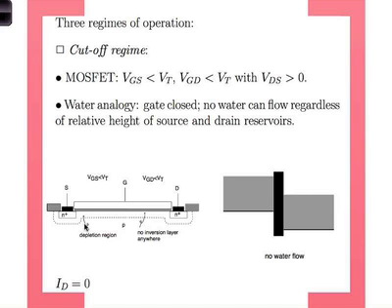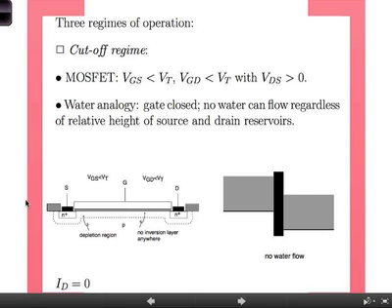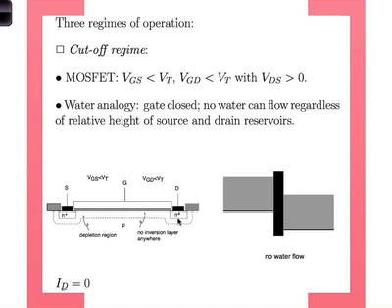So this is N plus. That's P. Think about this. P is grounded. S is grounded. So there's 0 voltage across this junction. So nothing happens across the junction. Now, if you think about this junction, this drain is connected to a positive terminal. The P type is connected to the ground. So it's reverse biased, right? This junction is reverse biased, so nothing happens. No current flow happens.